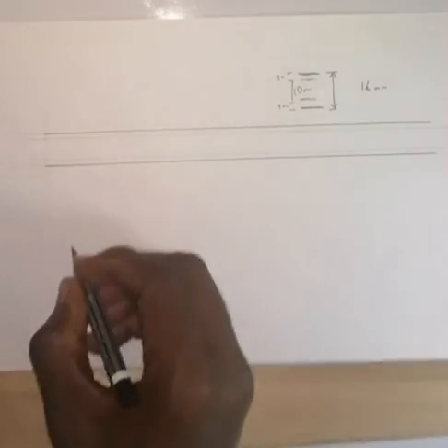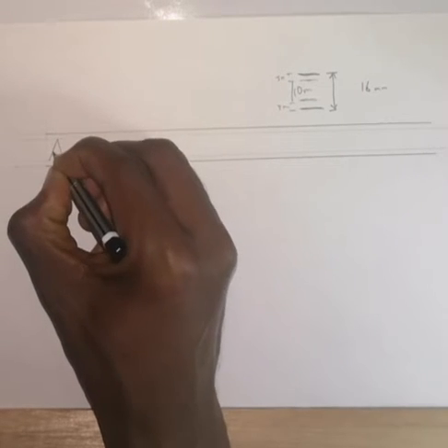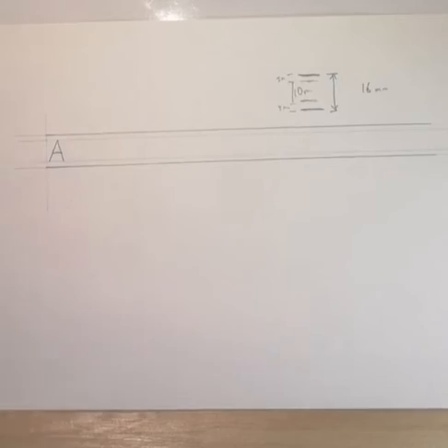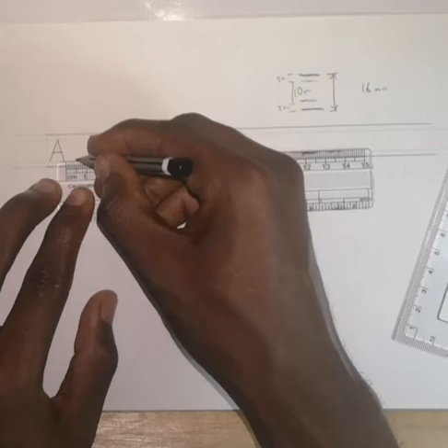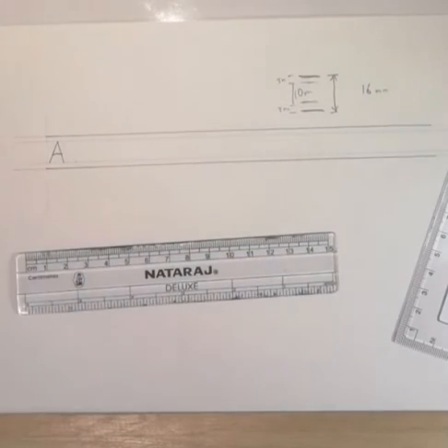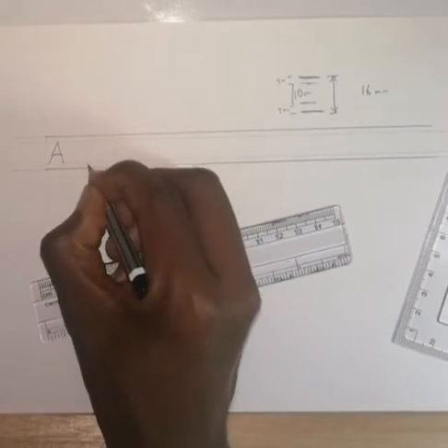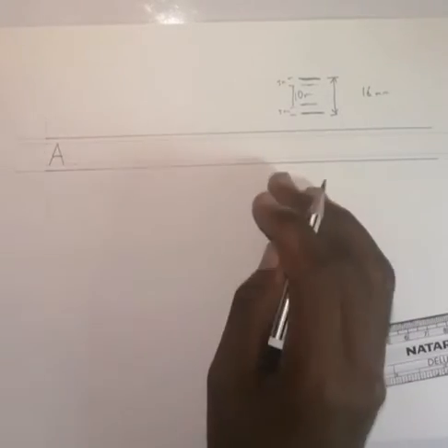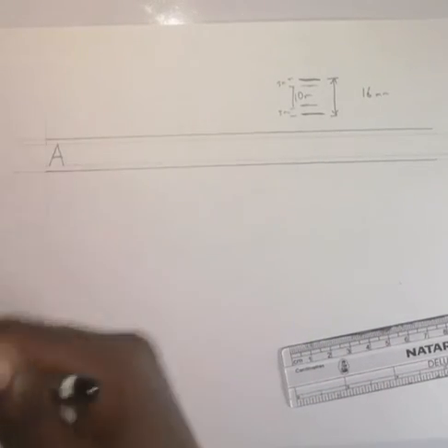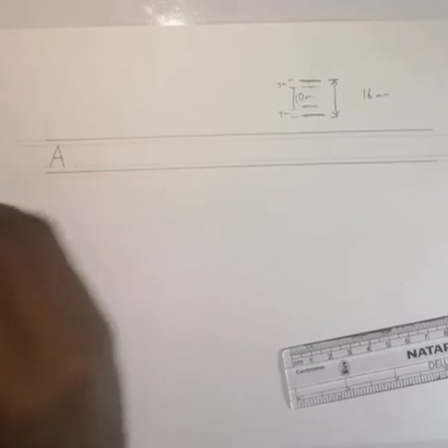Then you are going to letter. So you are going to let the alphabet touch. So that is A, right? Then try and leave a space of roughly about 5 mm, that's 0.5 centimeters between the alphabets. Maximum 10 mm, that is 1 centimeter. It shouldn't be more, it shouldn't be less. You don't need to measure throughout. You can just guess the distance. Just make sure that they are evenly spaced.